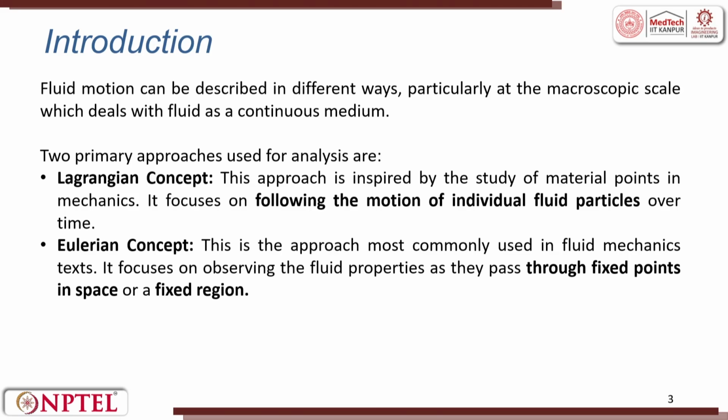Fluid motion can be generally described in different ways, particularly at the macroscopic level. Macroscopic means larger level, which deals with fluid as a continuum media. There are two approaches used for this analysis. One is the Lagrangian concept, the other one is the Eulerian concept. In the Lagrangian concept, we focus on following the motion of individual particles over time.